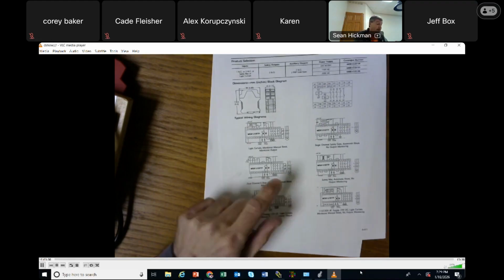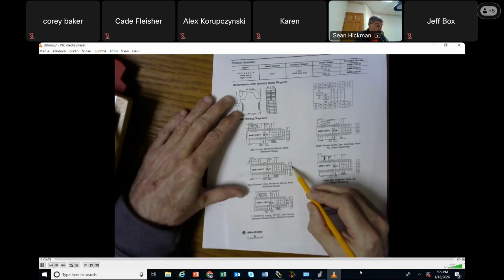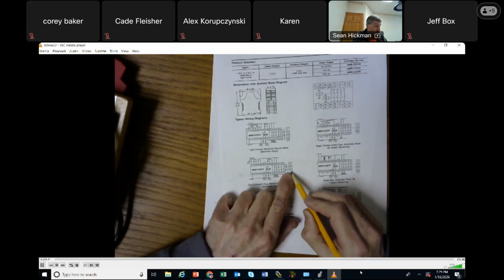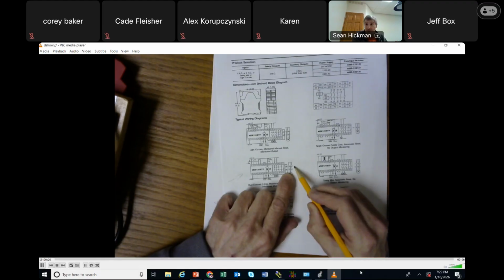So instead of having 1 contactor close line 1, line 2, and line 3, let's put 2 contactors right in series. Does everybody agree that that's what you're looking at right there? You're looking at 2 coils right in series that are closing together. It's called K1 and K2. The top one's the first relay, the bottom is the second relay. We have two contactors. All right.